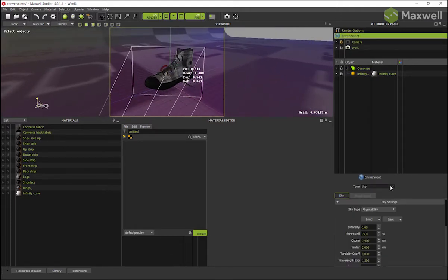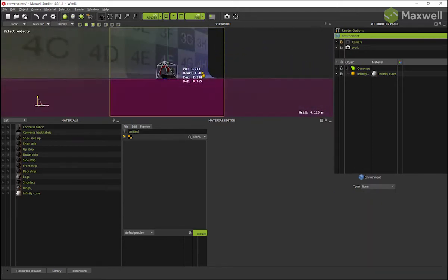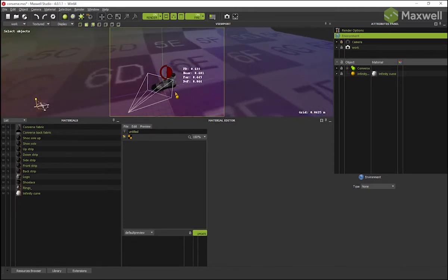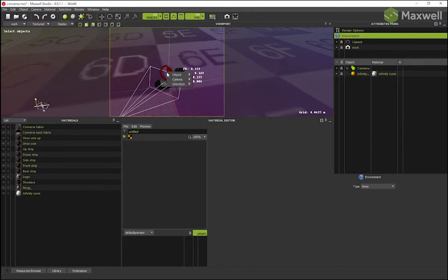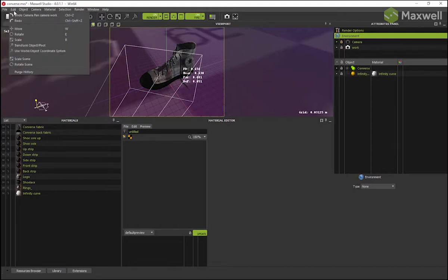To optimize your scene, try to use low polygon geometry for your emitters. A single polygon plane will do in most cases. This is a simple process, but requires testing until you get the illumination you want. Let's see how to do it quickly.